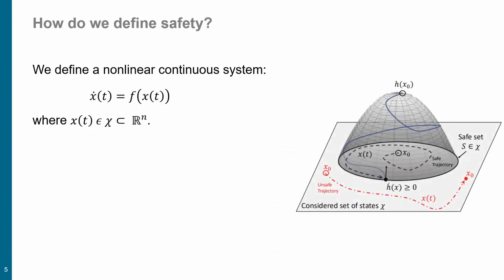And what we would like to obtain as a behavior is that for a system for which we have a model, and the model is maybe valid for a set of states, which we call Xi, like an aircraft model with a large data set. But we know the system can only be used in a certain constraint set, and this constraint set is the safe set. This is actually the operational flight envelope for an aircraft. And what we are trying to ensure is that the system always stays in this operational flight envelope, or say the safe set S.